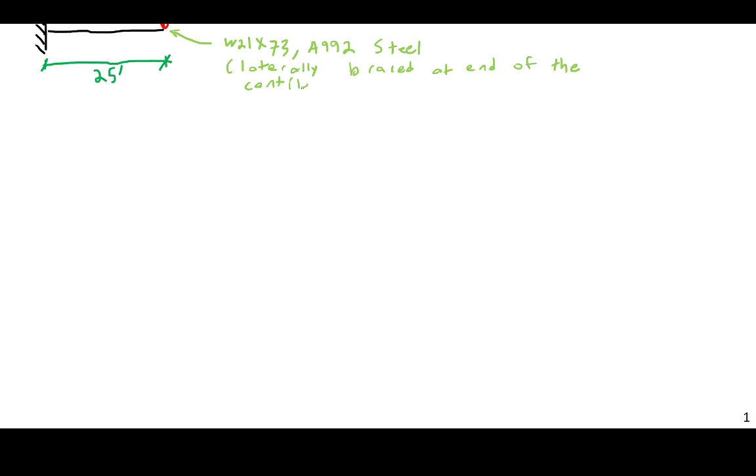If you read the notes on the CB calculation, if we did not assume this, if it wasn't braced, then whenever we have a cantilever, the CB will be equal to 1.0. Okay, so the very first thing I'm going to do is go to the first section in the steel manual, page 1-20, and gather up a whole bunch of section properties that'll prove useful throughout my later calculations.